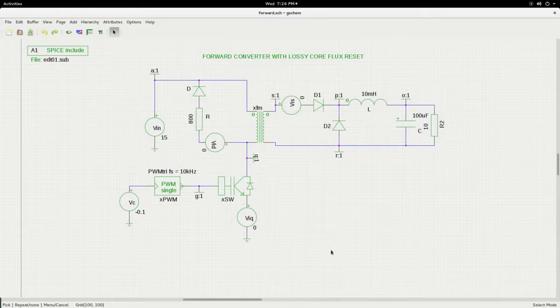So now you see I have made the changes which I said I would do, which is to put a source here, a source here, and a source here. Now observe also that I have put zero voltage value at all these sources. So these are just behaving like current sensors. Now I have put the positive in such a way that the current flows into the positive.